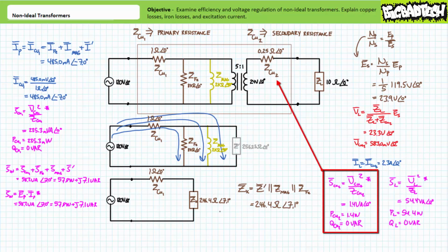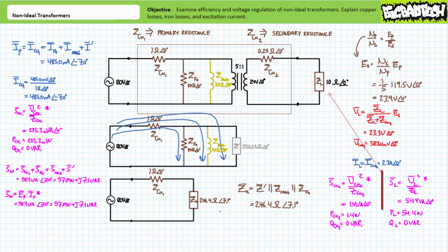Let's now examine power. The power equation demonstrates the small resistor accounting for the internal resistance of the secondary windings will consume 1.4 volt amperes of apparent power, all of which is being directed towards 1.4 watts of real power and none of it towards a reactive interchange. This isn't a terrible loss to the system, may only result in a small temperature rise.